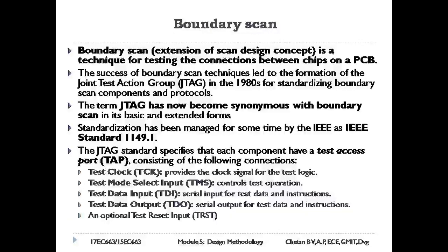Boundary scan. Boundary scan, an extension of the scan design concept, is a technique for testing the connections between chips on a PCB. The idea is to include scan chain flip-flops on the external pins of each chip.